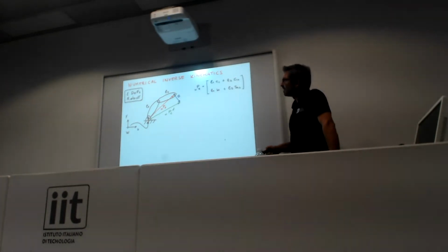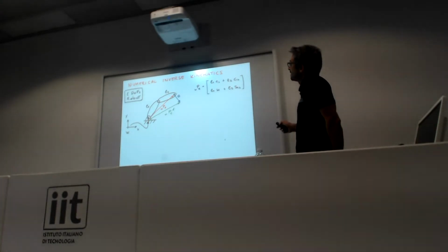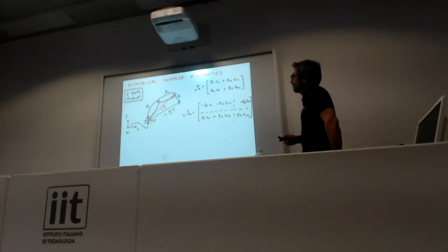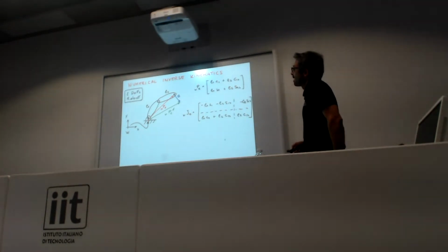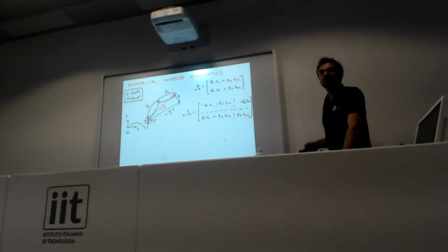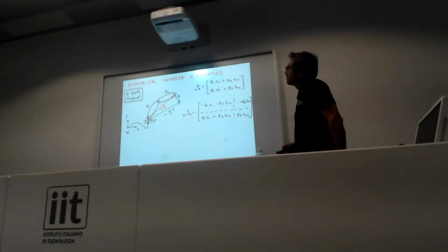This is the forward kinematics of the end effector: the length of the first link times the cosine of the first joint, plus the length of the second link times the cosine of the first joint position plus the second joint position. If you differentiate with respect to the first and second joint positions, q1 and q2, you get the Jacobian. I guess you know this quite well.